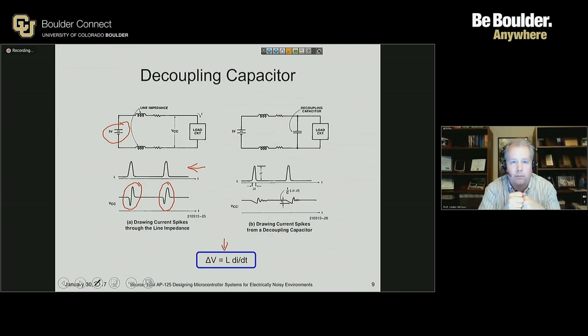And if I do that on certain types of chips, especially processors, the processor has lost control and the state machine that's governing its function is not necessarily where it should be. Our job is to try to maintain control over that state machine at all times, and we do that by giving the processor a clean voltage supply.